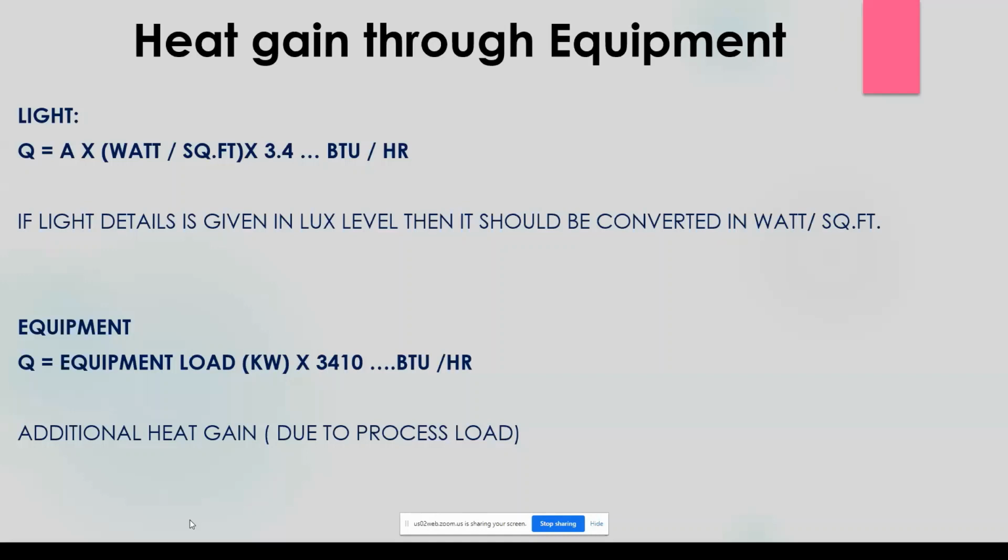And if you are taking the battery, the battery also liberates heat, so you are doing some cooling for battery rooms. As of now I am just taking this as generalized because of the limitation of time, because for each and every equipment you need to see the type of use. Whenever I say process load, we need to be very cautious, try to understand the equipment and put it into the equipment load sheet.